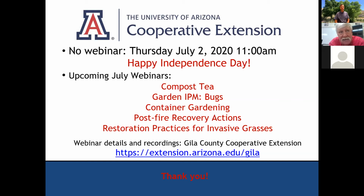So the high heat doesn't seem to be a big issue. If you can go out there and maintain them a little by cleaning them off, that will obviously help your output. But as you know, voltage decreases with temperature when it's high heat, and when it's colder it goes up. So the big thing in planning is saying, I know I'm going to have a voltage drop-off because of high heat, so I've got to plan for that and maybe add more modules to my system.